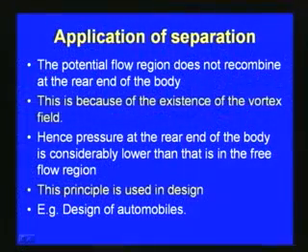So, with respect to the boundary layer separation, you can see that the potential flow region does not recombine at the rear end of the body, as we have already seen in the various cases. This is because of the existence of the vortex field. We have seen that after the separation takes place, there is a possibility of a vortex field within the wake, so that the potential flow region does not recombine at the rear end of the body.